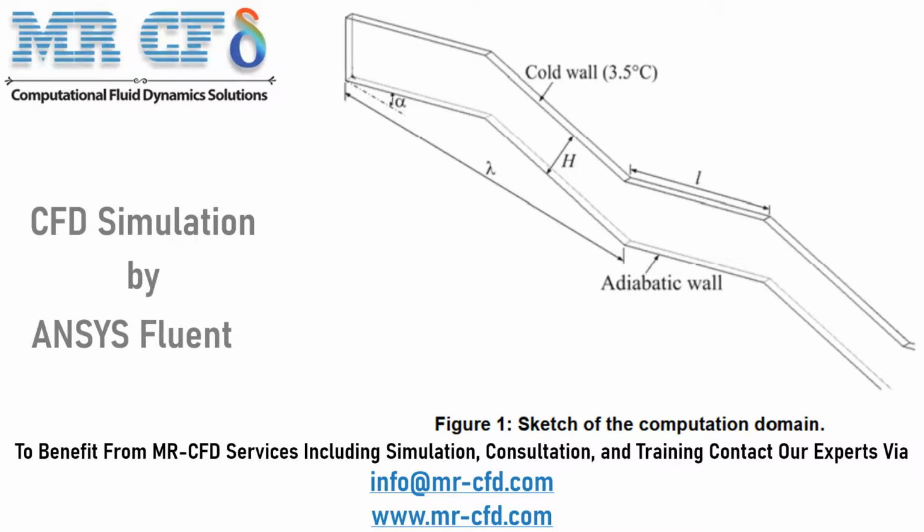Therefore, due to the low Reynolds values, the flow in all models is defined as laminar. The inlet velocity of water flow in different models varies based on Reynolds value, but the inlet water flow temperature in all models is equal to 293.15 Kelvin. The lower wall of the zigzag channel is insulated and the upper wall has a constant temperature of 276.65 Kelvin. The main purpose of the problem is to investigate the amount of Nusselt number in the vicinity of the upper wall of the channel.